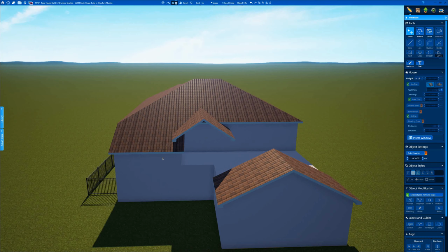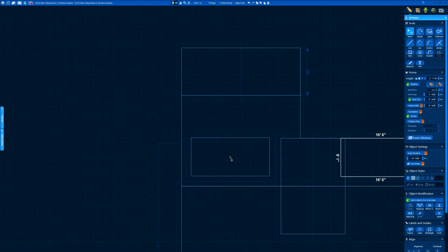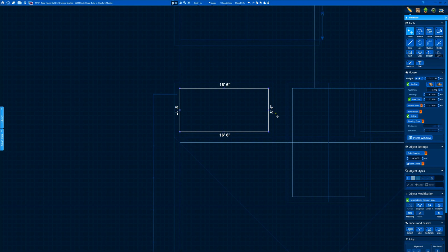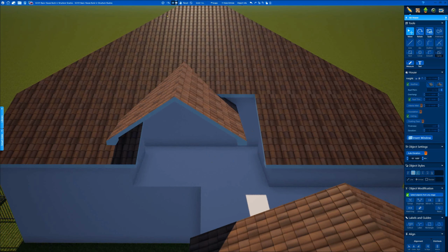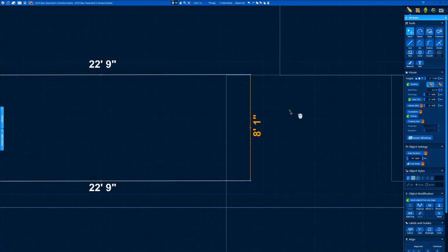Now we need another shed section just like this one. So we got a lot of copy paste also, just kind of save some time. You already have squares, you know it's snapped because your grid snaps are on, so you can just snap it in place. Now for some reason the program will drop this down, so you have to go back up to your plate height of your lower wall, which is 10 feet. And we're just going to roll this over here.